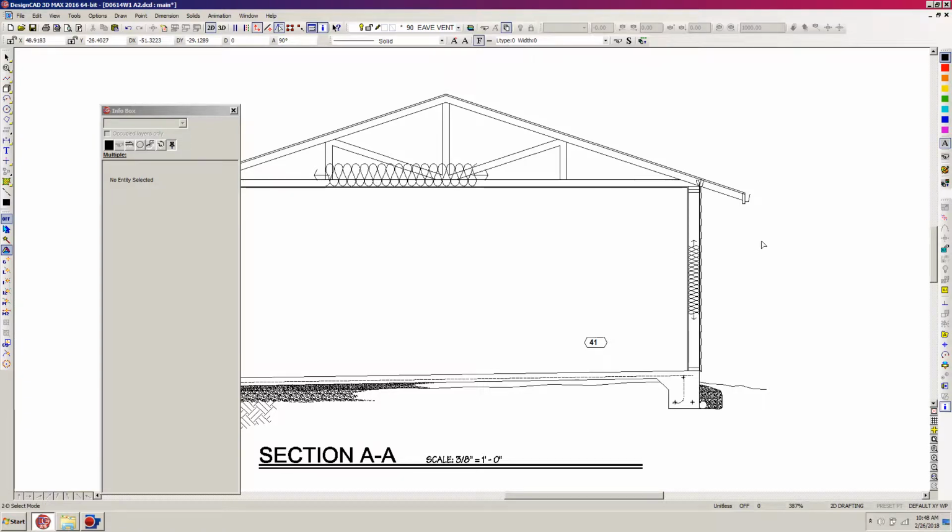So what I'm going to do right now is activate the arrow command by holding down Shift and hitting the period key, which is the greater than, and so you can see the arrow here, 0.35, which is the correct size. And now I'm going to just right click, and I'm already in orthogonal mode. I want a nice straight arrow here. I'm just going to go to about the middle of the stud and just left click and then hit my scroll button to initiate the command.